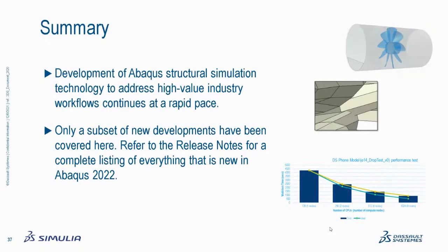Okay. Any linear dynamic enhancements? So I kind of partially answered that question with my summary. Yes, there's a lot of them, related to the AMS eigensolver, acceleration there, damping, substructures, a whole bunch. We could probably have a whole presentation just on those, so I have to refer you to the release notes for a comprehensive listing of everything that's new with linear dynamics.